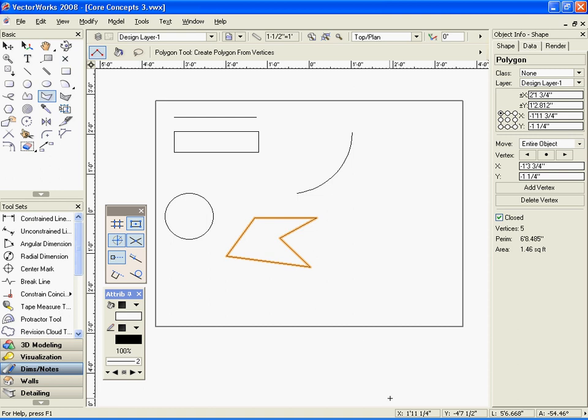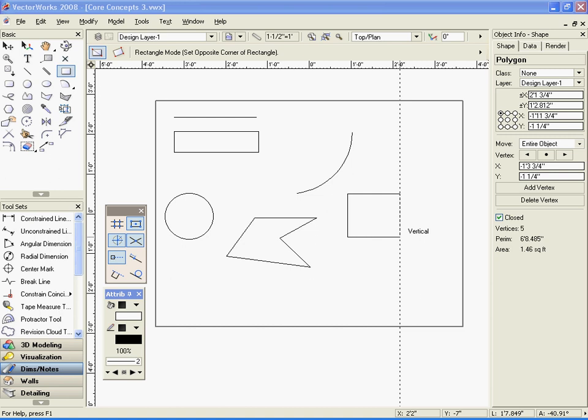As I'm drawing, the message bar at the bottom right of the screen provides information about the cursor position. Numbers can also be entered in the floating data bar fields. With a tool selected, click in the drawing window to start, then press the Tab key to activate the floating data bar. Enter a value and press Tab again to lock it in, moving through the fields to enter more values or accept the ones already entered. Repeated tabbing will move the focus through the fields, allowing you to change entries. When finished, press Enter to create the shape.